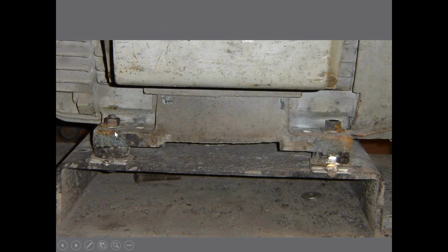It should be within 75% thickness. I've been in companies where it has to be 100% thickness of the foot of the motor. It's only half as thick as it should be, so it's going to create vibration issues. But here again, they had alignment within 1.5 thousandths in all three planes. It took them 7 hours to get there. They had smiley faces in all three planes. I don't know what the smiley face represented as far as accuracy. They didn't use torque wrenches on the nuts. But again, not precision work, but they obtained some precision results.